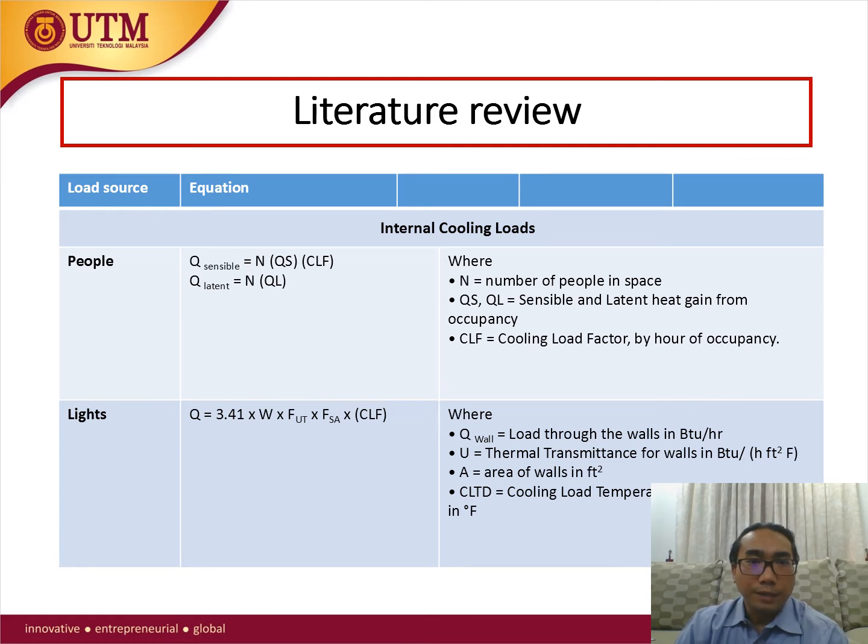For the lights, the primary source of heat from lighting comes from the light emitting elements. Calculation of this load component is not straightforward. The rate of heat gain at any given moment can be quite different from the heat equivalent of power supplied instantaneously to those lights. Only part of the energy from light is in the form of convective heat, which is picked up instantaneously by the air conditioning apparatus.